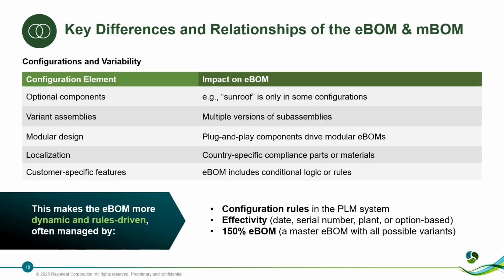The eBOM includes conditional logic or rules. The configuration rules are in the PLM system. The effectivity is driven by date, serial number, revision, plant, or option-based. The 150% eBOM is the master eBOM with all possible variants.